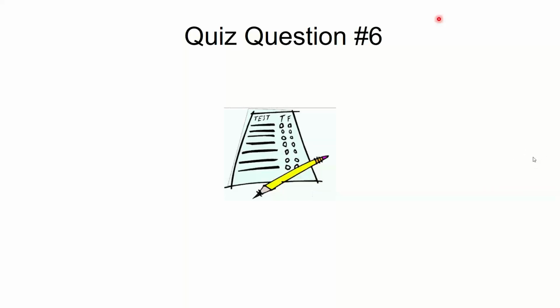So here's the good news. I clicked the button so fast in a hurry that I messed this up, so the good news is you all have it right. I'm going to go in and artificially change your answer. The answer is false. That is not the sweet spot. The sweet spot would be 40 to 60%. If you're above 60%, bad crap happens. We mentioned it a couple minutes ago, and we also mentioned early on that I want to keep things below 60% for comfort and 65% and below for mold growth reasons. So the answer is false.